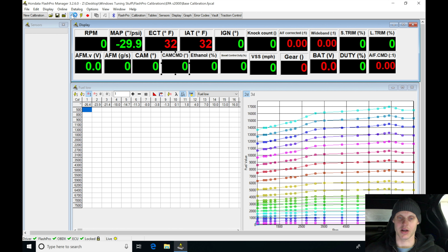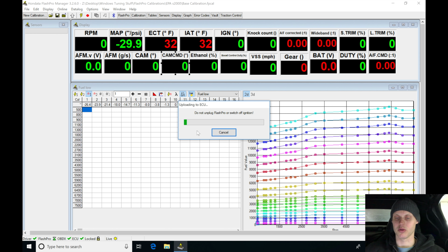So I'm going to hit upload, and we're going to see that it goes through the upload process. It takes about 60 to 90 seconds to do the first upload. It's always going to be this time-consuming process. So we'll just be patient while it does this, and as soon as it's done, we're able to hit F10, which is going to allow us to get live with the ECU and start to monitor some of the information.